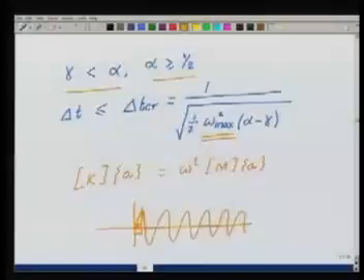Okay. So remember that if I am doing something in the spatial regime, that is, I am trying to refine the approximation there, I have to do a corresponding job in the temporal regime. Further, in the spatial regime, I have a rate of convergence. If I do not get a similar rate of convergence in the temporal regime, I have to ensure my time steps are small enough.